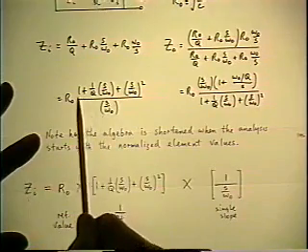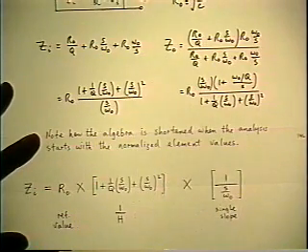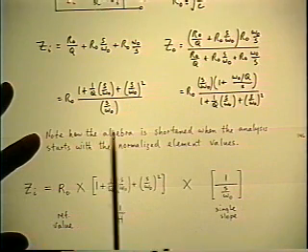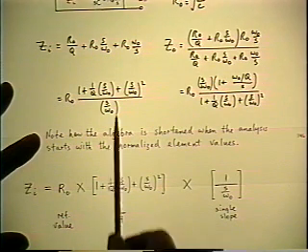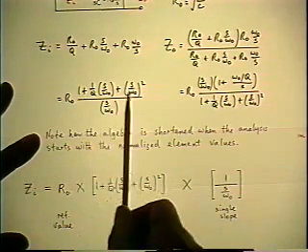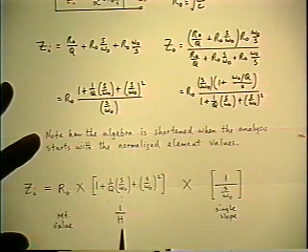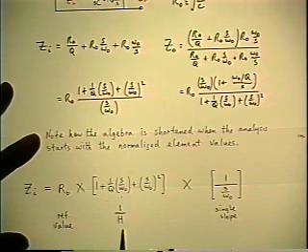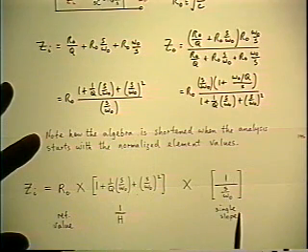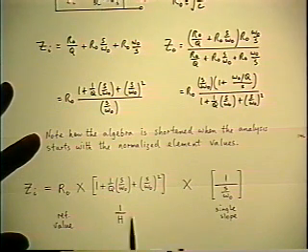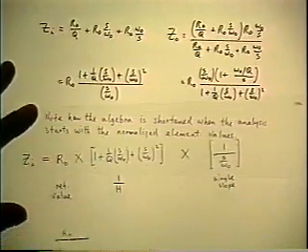The second factor is the quadratic equation. We know all about the properties of the quadratic, and the only difference this time is that it's in the numerator instead of the denominator where it was in the voltage transfer function. But we know what the relationship is. It's a vertical inversion. So the quadratic can be interpreted simply as the reciprocal of the voltage transfer function. It's the same formula. And finally, there's the 1 over s term, which is the third multiplier factor. So we already know the shapes of all of those functions, and all we have to do now to multiply them together is to apply superposition on the double log scales.